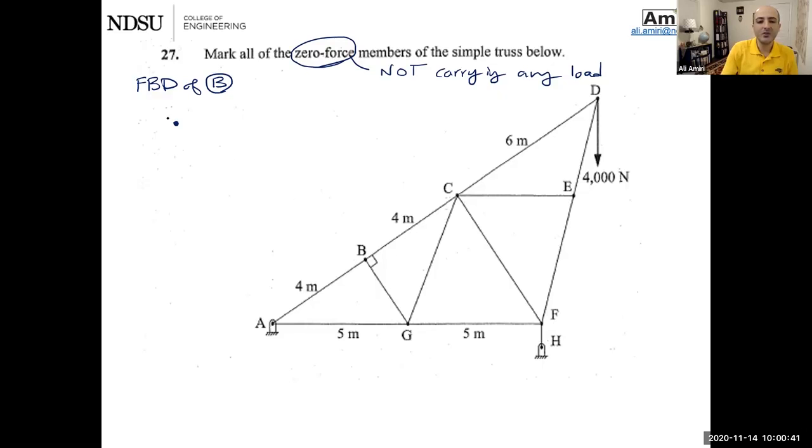So I have a force going BC this way. I have a force going this way, BA. You can put them in compression or tension, meaning going away or coming in. Doesn't matter because I don't know it. I'm just always used to drawing in tension. And BG. Okay. I'm going to turn my axis again, X and Y, and write summation of forces in Y direction being 0.